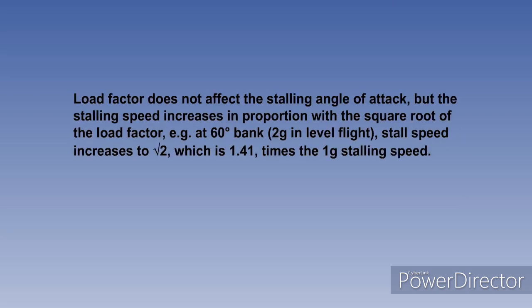In brief, load factor does not affect the stalling angle of attack, but the stalling speed increases in proportion with the square root of the load factor, in the same way as it does with the weight increase, since G is an effective increase in weight.